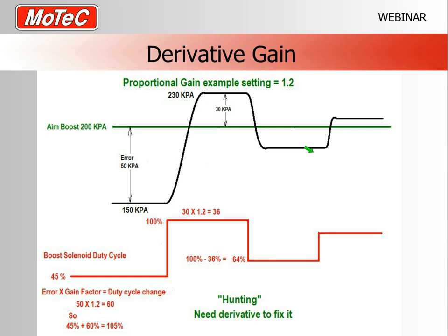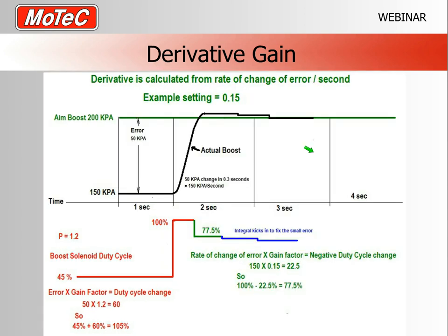So when the proportional responds nicely, you need to have some derivative in there to help it stop from overshooting. So this effect where the derivative pulls duty out as it starts responding quickly. So you leave the integral at 0 and stop that confusing things, and just work between the proportional and the derivative.